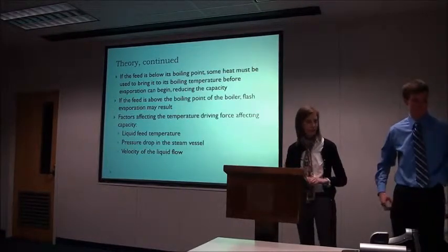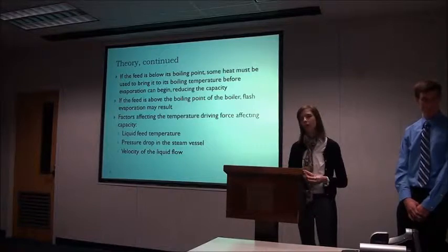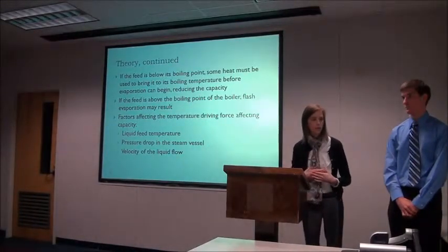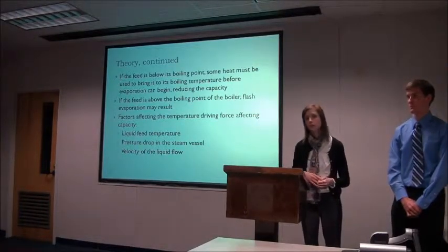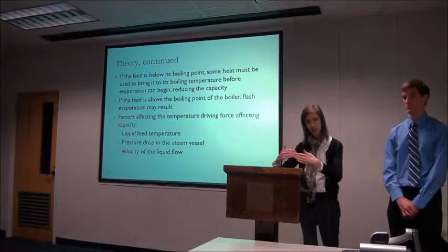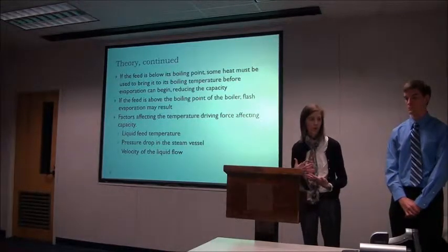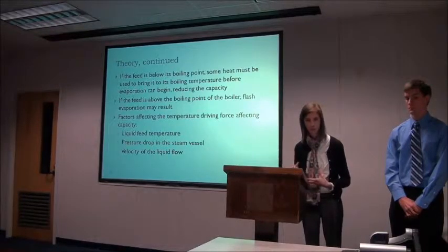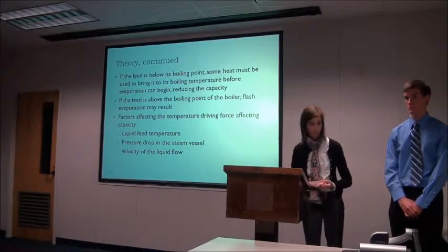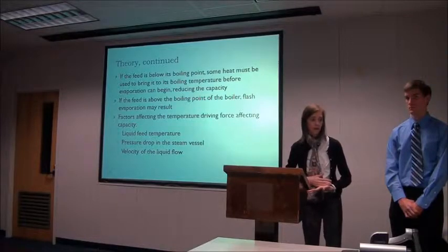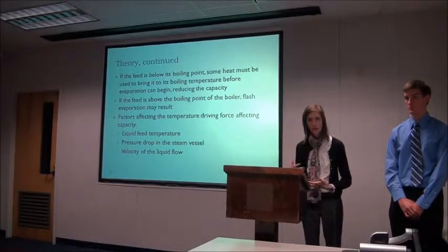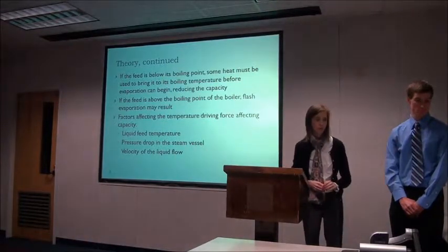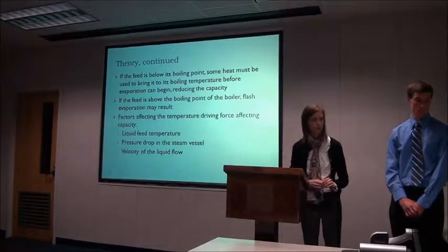And one more slide of theory. So some factors affecting the capacity would be if the temperature of the feed is below the boiling point, some of that heat has to go into raising that temperature. Therefore, your overall capacity is reduced because the temperature must be raised in order for the boiling and the evaporation to begin. However, if the feed is above the boiling point, you may have flash evaporation.